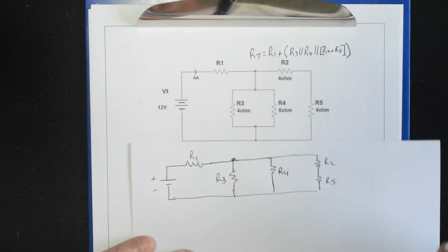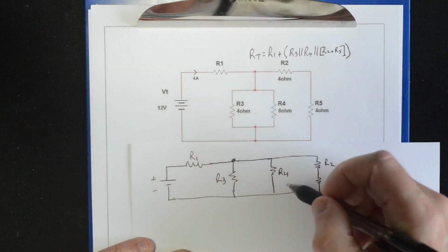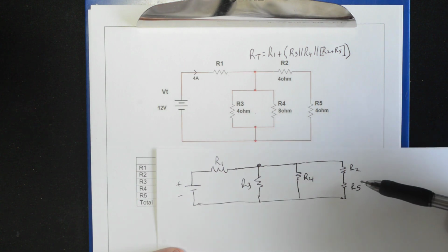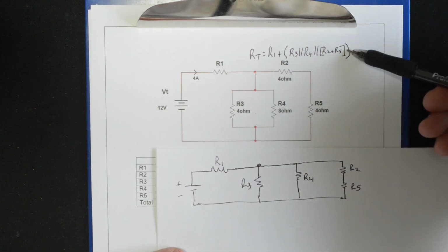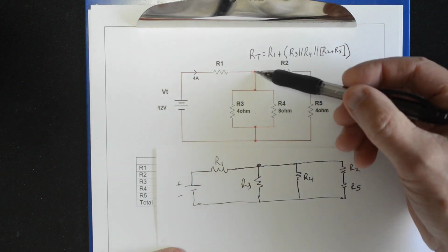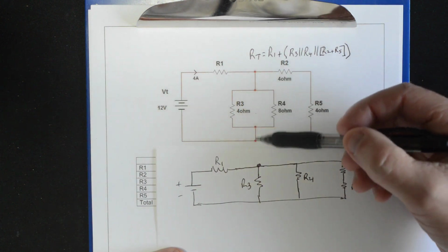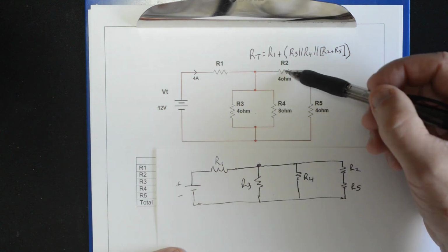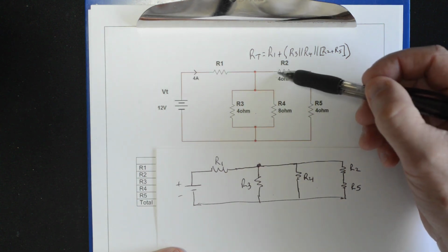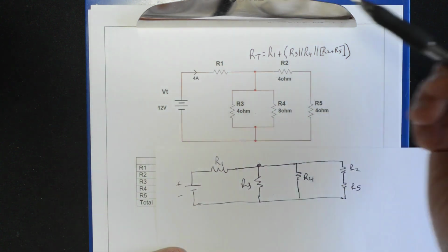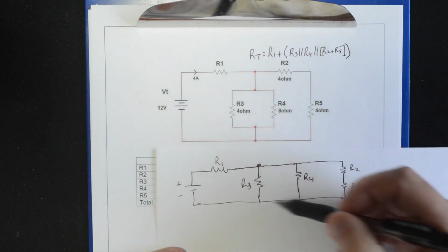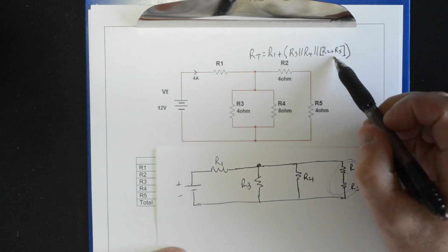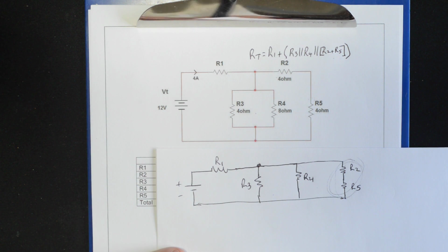So this circuit and this circuit are electrically the same. It should be easier to translate this back into this if you look at it this way. I just put this little thing here in an island with two little connection points to make it not look like this. And then all I did here is wrap it around the corner. But if I put it side by side here, not changing this branch at all, you can tell that this is nothing but a parallel circuit. You just have to know that you have to add those two together first. That's what that's for.